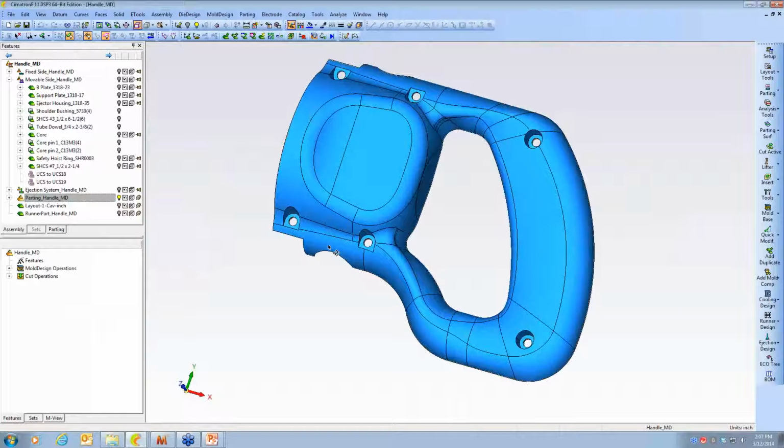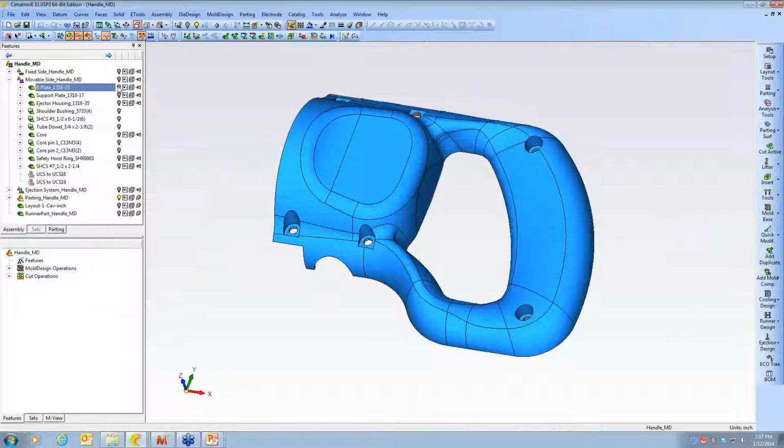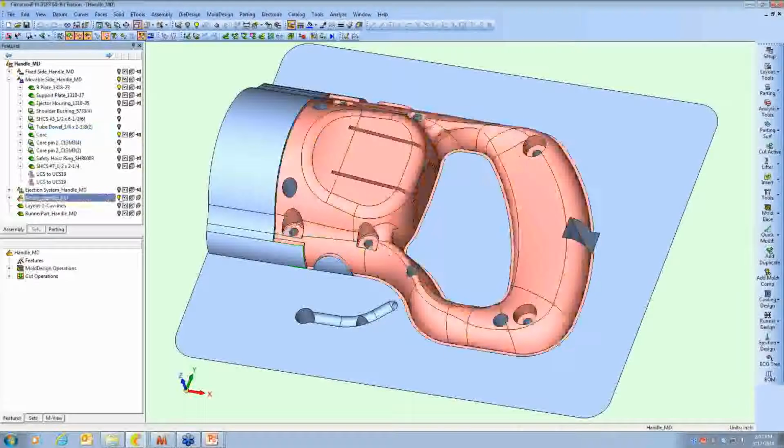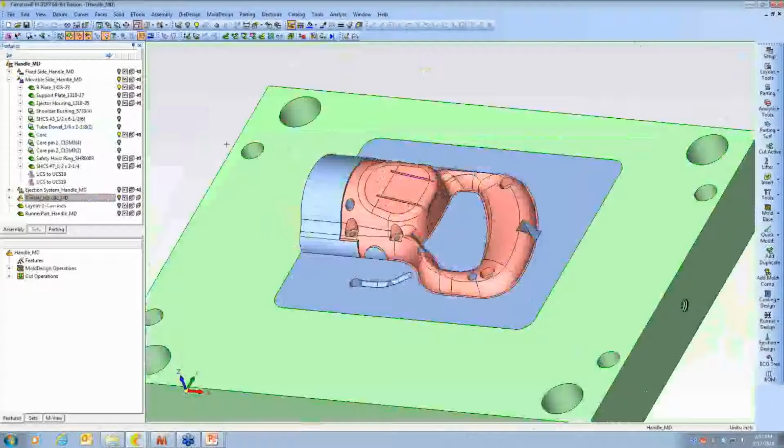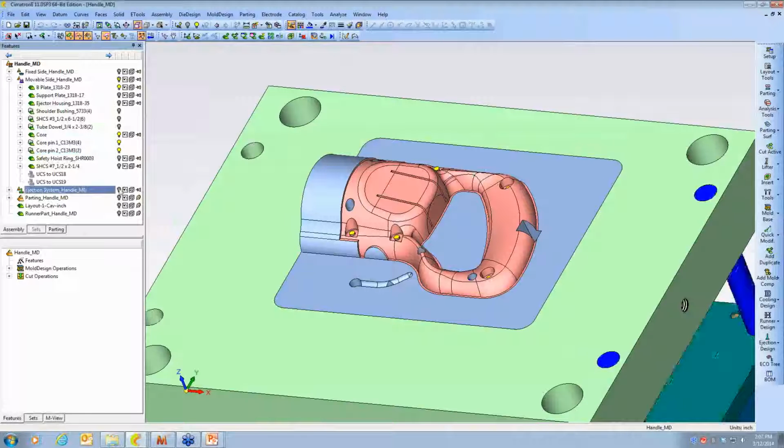The mold design is in process. Besides the cavity and core development, this side of the tool has seen the addition of 6 core pins and a standard lifter assembly. That's for an undercut feature on the part. And in addition, the design of the ejection system has already started. As important to productivity as good cooling is, if the part can't be ejected, the mold just isn't going to work. So a few important ejector pins are already in place here.